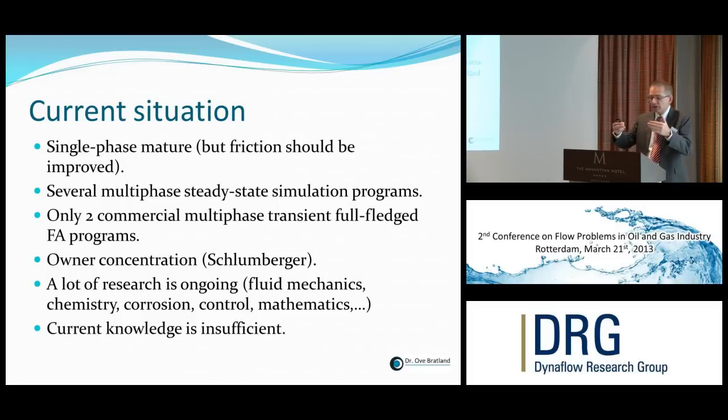It comes down to a fundamental problem that the friction diagrams try to model the roughness of a surface by simply modeling how high the roughness is, the distance between peaks and valleys of roughness on a pipe. And that isn't a good enough way to describe a surface.